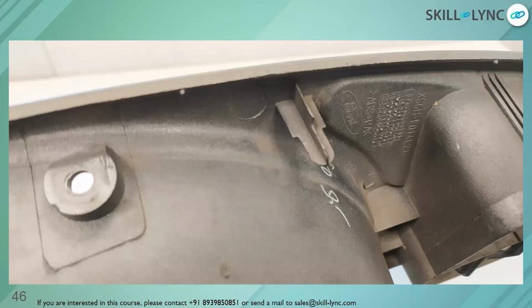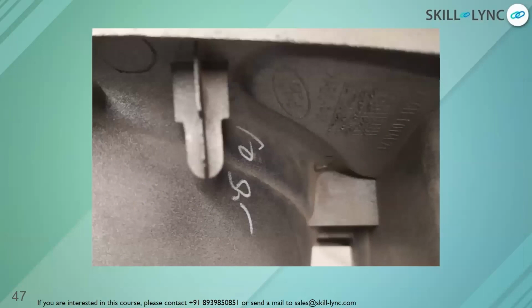And then finally, you will be having the other operations performed, like your push pins, etc., provided accordingly for the final assembly with respect to your sheet metal parts. Okay, so hence these kind of components are being used. Sometimes we might not find much of locators in your plastic components, and then these screw bolts and other things are actually going to perform the function of a locator. Okay, so these are some of the things which we need to look into while we have an understanding about plastics and the plastic features. This is another image with a four-way locator. Hope you can see it properly.